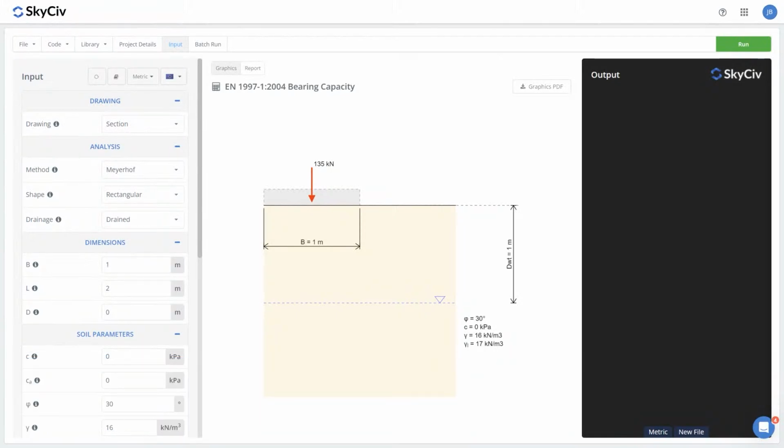Today I just wanted to talk about bearing capacity, what it is, and how we can design for it. So first of all, the bearing capacity of a soil is its ability to resist shear failure under vertical loads, which can come from structures like strip footings, pad footings, crane outriggers, basically any structure on the surface of our soil applying a vertical force could develop a bearing failure, and we need to be able to design to ensure that we can resist this by running these bearing capacity checks.